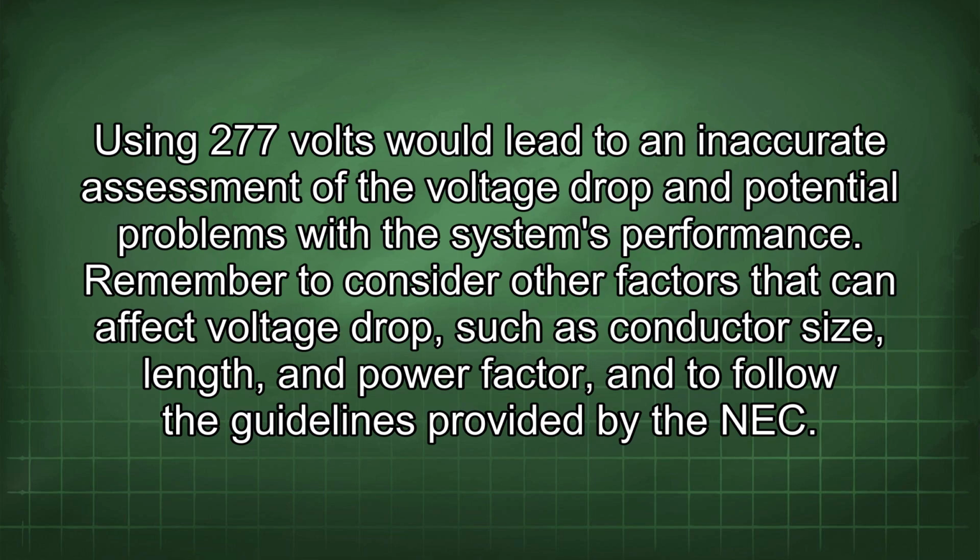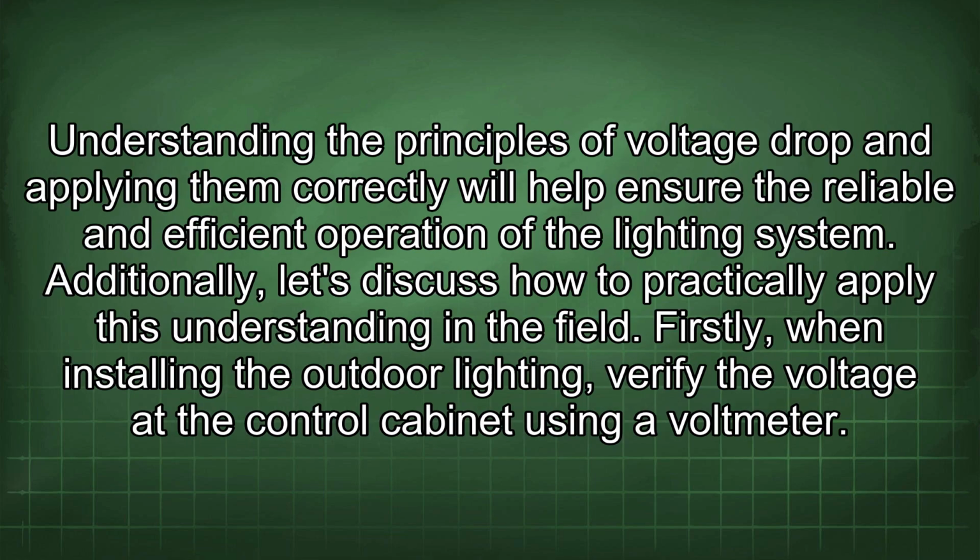Remember to consider other factors that can affect voltage drop, such as conductor size, length, and power factor, and to follow the guidelines provided by the NEC. Understanding the principles of voltage drop and applying them correctly will help ensure the reliable and efficient operation of the lighting system. Additionally, let's discuss how to practically apply this understanding in the field.